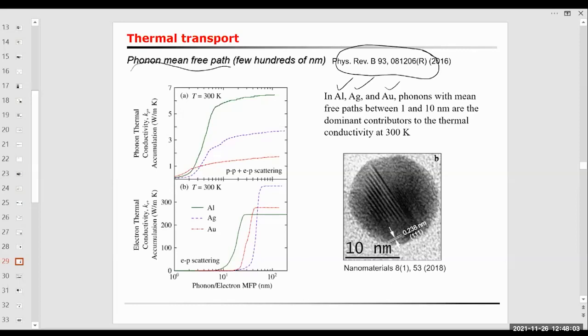See, you might put it on paper or in software, but in reality these nanoparticles agglomerate because of the interactions they have, and they become bigger particles. So dispersion, mono dispersion, is very difficult. You also have to find surfactants and other things to have a mono dispersion. Once mono dispersion is there, you can have manifold effects.